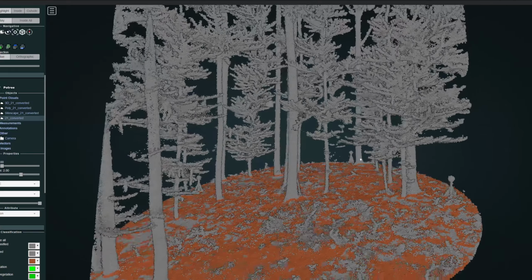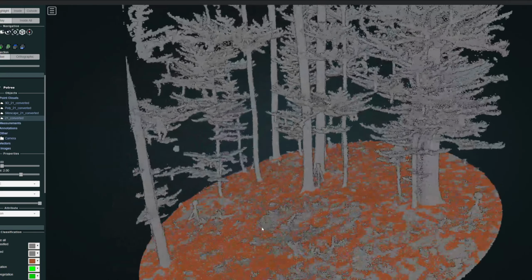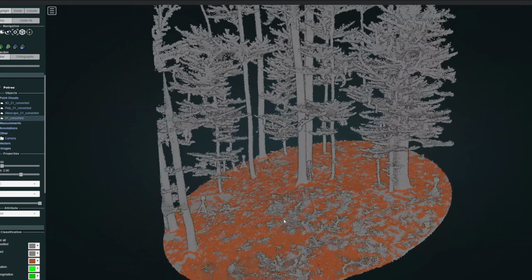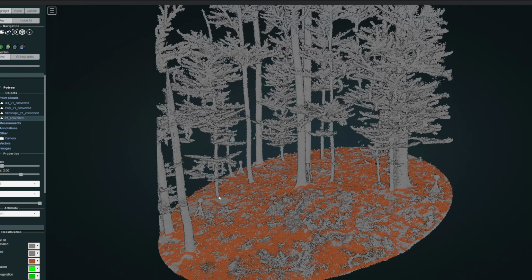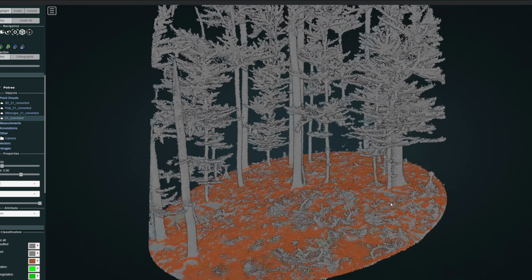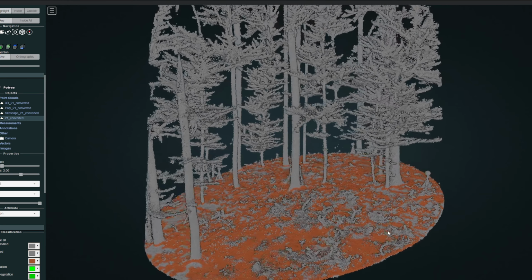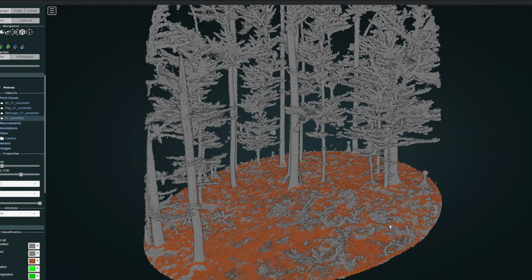Those are co-registration spheres. And when we talk about trying to utilize terrestrial LiDAR or any technologies like that, they rely on having these targets so that they can calibrate where they are, compute the geometry here with known objects of a known size, and known reflectance, so that they can figure out any error associated. And these spheres are quite expensive, actually. We paid several $1,000s for a set of 6 of them, so that we could have exact size, known albedo, known reflectance, but what they do is give you that calibration and error assessment.